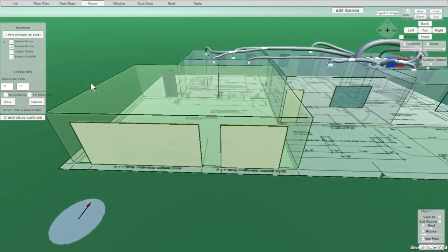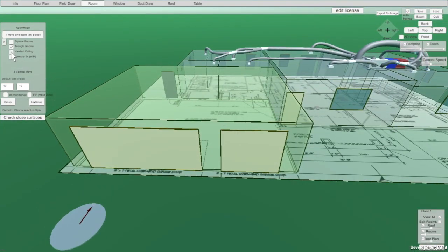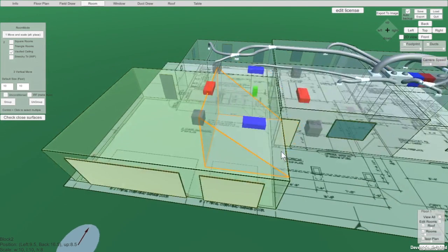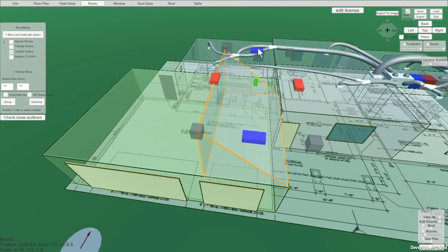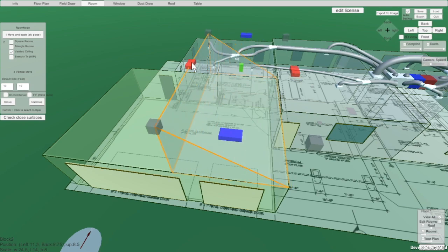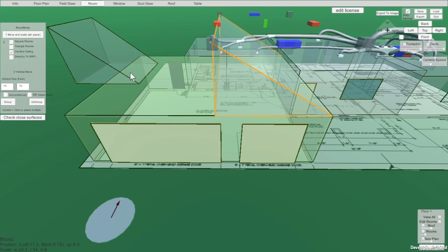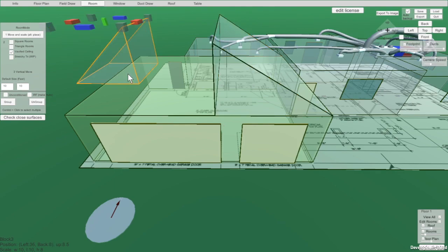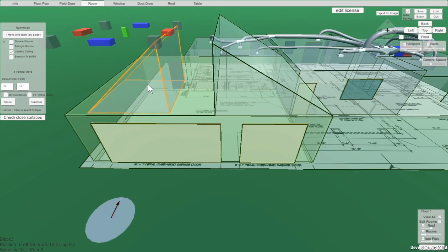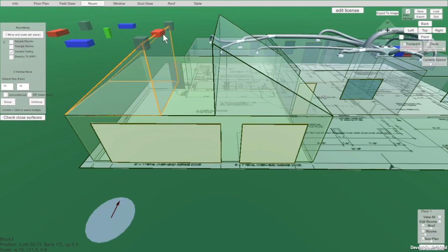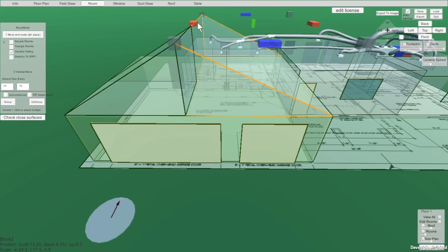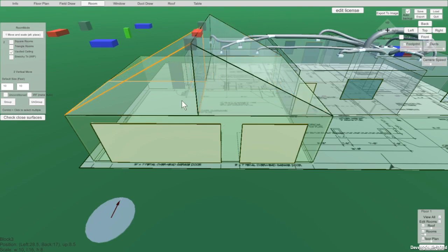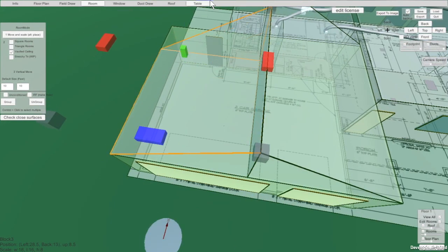The other thing that it does is vaulted ceilings. So I'll show you how that goes. They're an angled ceiling, and so if I want to put a vaulted ceiling on this garage here, look something like that. You can get it to line up like so. Stretch it out, stretch it across, and then if you want to do a peak vaulted ceiling that peaks in the middle, put 2 of these on here, and let's see if I can find the approximate middle here, like so, and stretch it out this way.